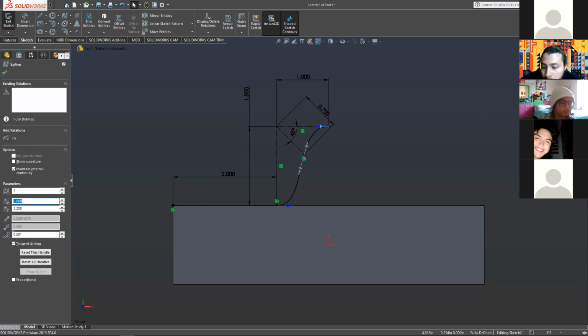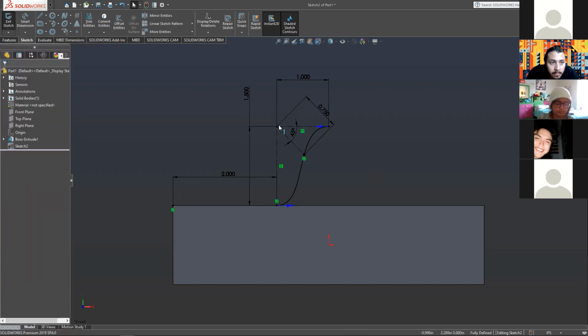The angle value we're setting to 0 is a relative value. So sometimes you'll set it to 0 and then it'll invert itself. If that happens, set it to the opposite of whatever you set it to. So instead of 0, set it to 180. If you have it at 90, set it to -90. You can put a little negative in there and it'll be like, I get you, man. And then bam. All right, so there's our perfect little shape, our little S. It's very nice.